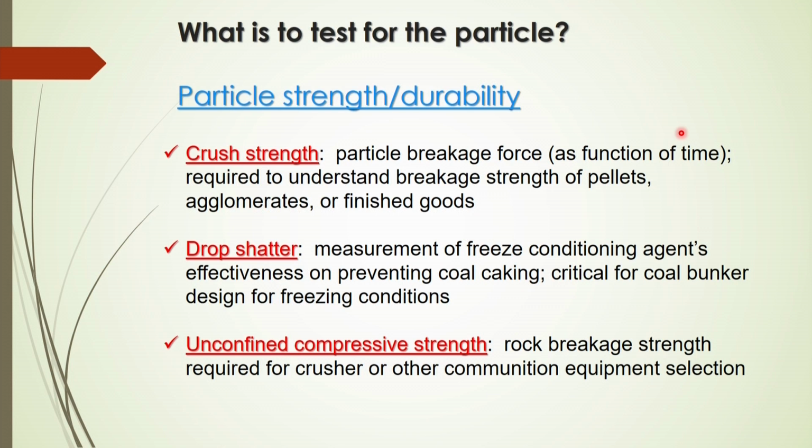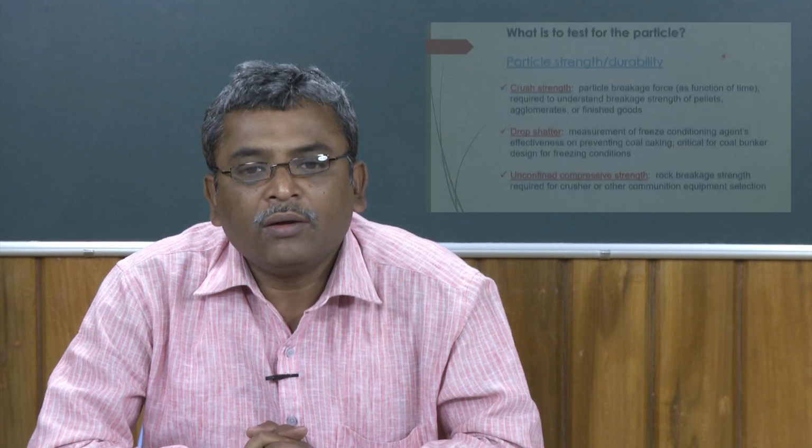It depends on particle material, of course, the durability of the particle. Whenever particles are used in a fluidization operation, you will sometimes see the particles break down at a high velocity. In that case, the strength of the particle is important. Now, particle breakage force as a function of time is required to understand the breakage strength of the pellets.